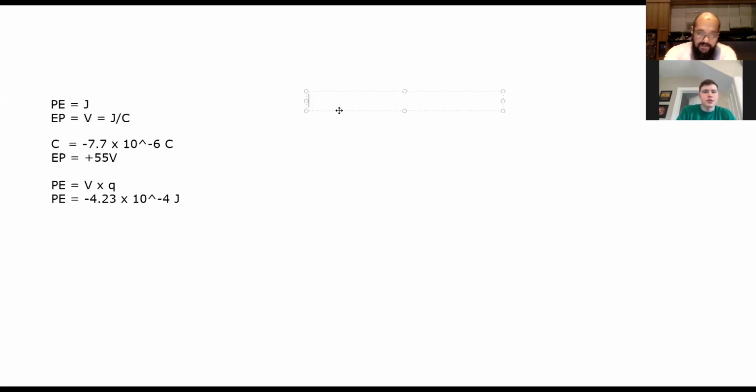And we might get this done. So question number 9. 2 parallel plates connected to a 200-volt power supply are separated by an air gap. Okay, this air gap thing is actually very similar to what happens in a capacitor. How small can the gap be if the air is not to become conducting by exceeding its breakdown value of E equals 3 million volts per meter?